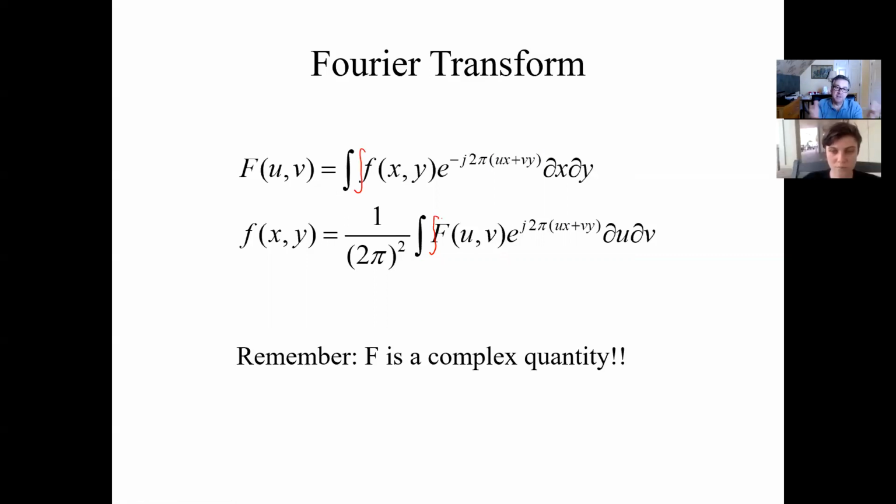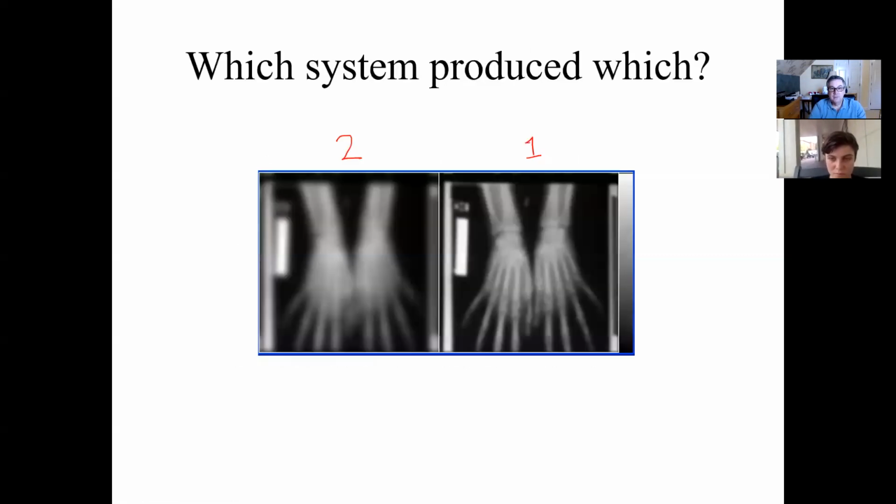Okay, and so there will be high frequency, low frequency content, and the general idea is that any image can be expressed as a set of pixels. That's one way of expressing it, but it can also be expressed as a set of frequency elements, frequency basis functions, each of which is different and orthogonal to the others, as basically this image could be a weighted sum of all of those different frequencies.